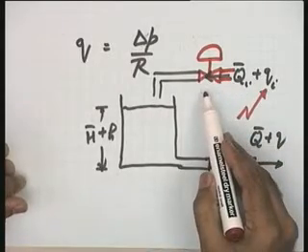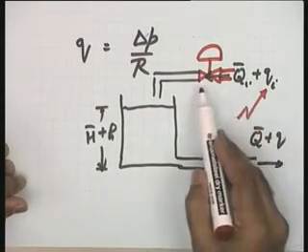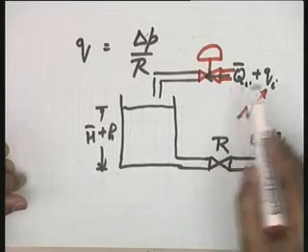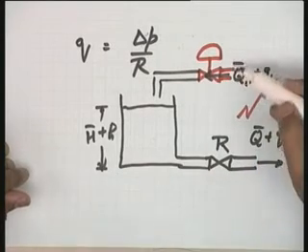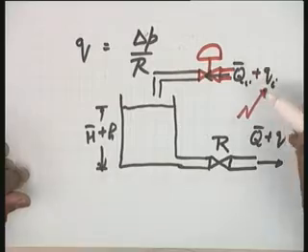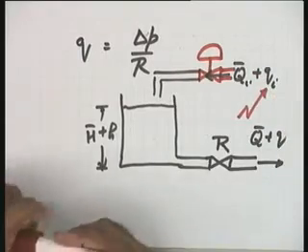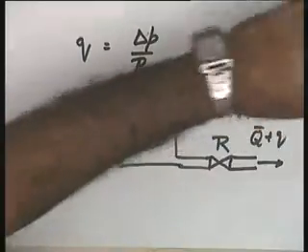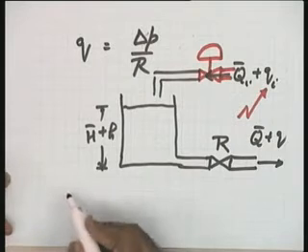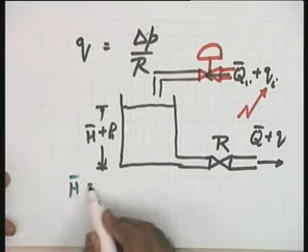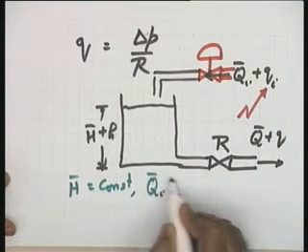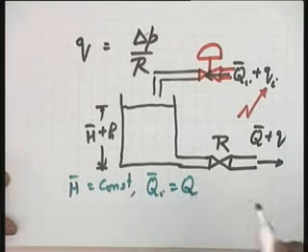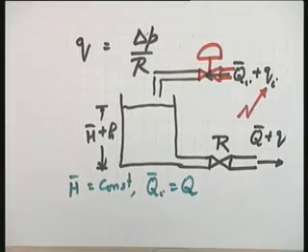So, there is a controlled valve, and through this controlled valve you are going to have the flow Q I bar plus Q I. Okay. So, with respect to steady state, what will happen at steady state? Please help me. I think the situation is very clear. At steady state, your H bar is equal to constant and Q I bar equals Q I equals Q. This becomes the steady state situation.